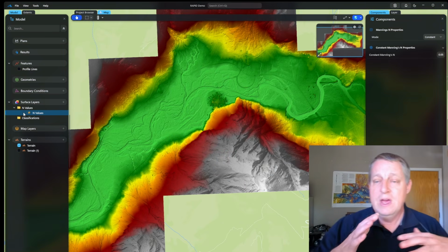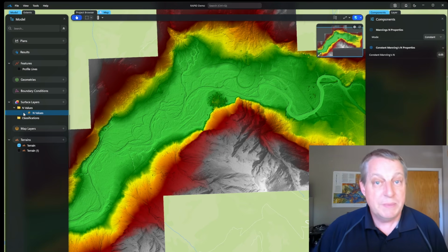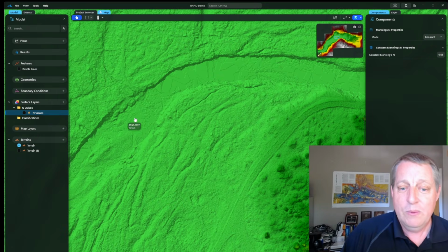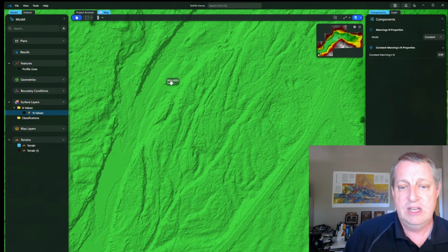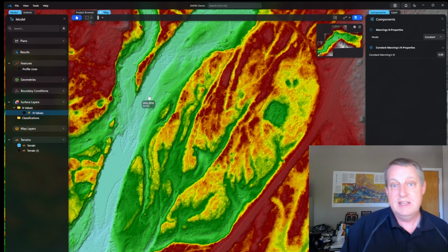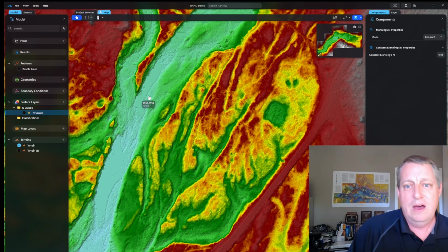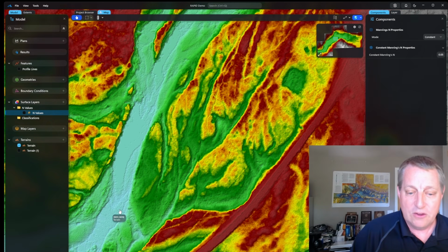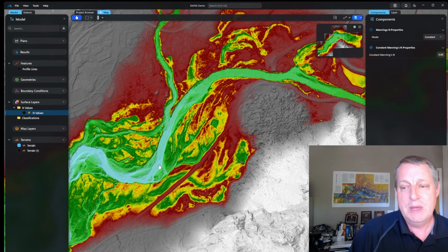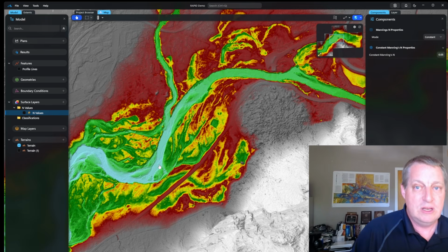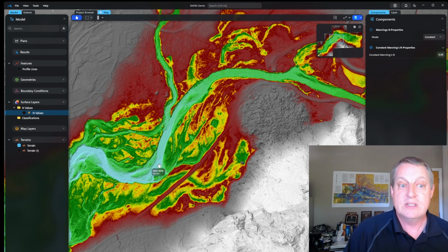Okay, so now we've kind of done the simplest possible spatial representation of the landform. What about channel? What about bathymetry? Well, this river actually doesn't have bathymetry data, and usually that's a big no-no, but this is a mountain gravel bed river, and so if you fly your LiDAR at low flow, really all you're missing are the pools, so it's actually going to be good enough for flood risk management. You wouldn't do this with, say, the Missouri River or a deep sandbed river where you absolutely need to go in and cut the channels. We'll do other videos on how to work with that.